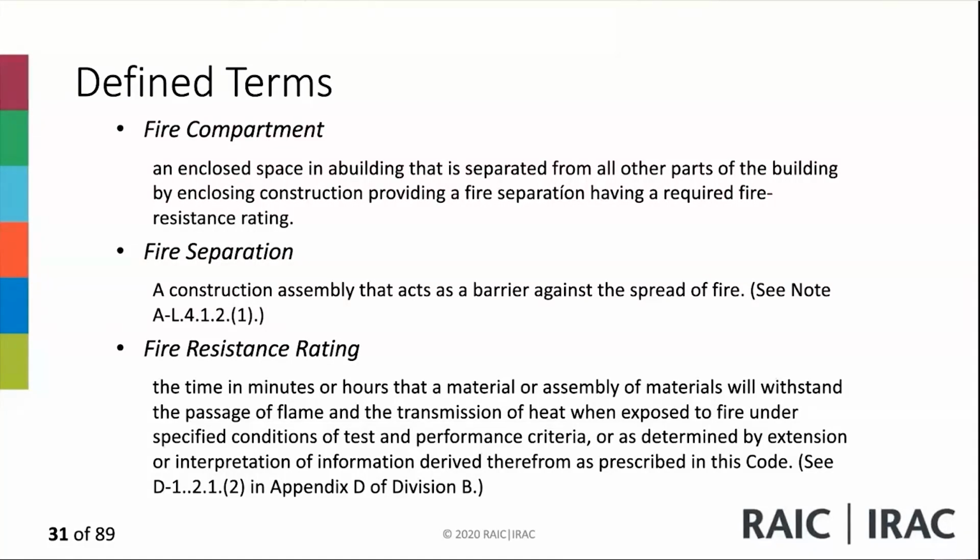And this is critical when we have the provisions for sprinklers to replace fire separation requirements. There is the critical element of smoke that needs to be addressed with the evaluation. You cannot just look at the fire transmission in terms of heat transmission, thermal transmission, flame through. You need to take a look also at the element of smoke and address that head on. And if you see an evaluation that does not address it, then it is an issue for the NFC. Okay?